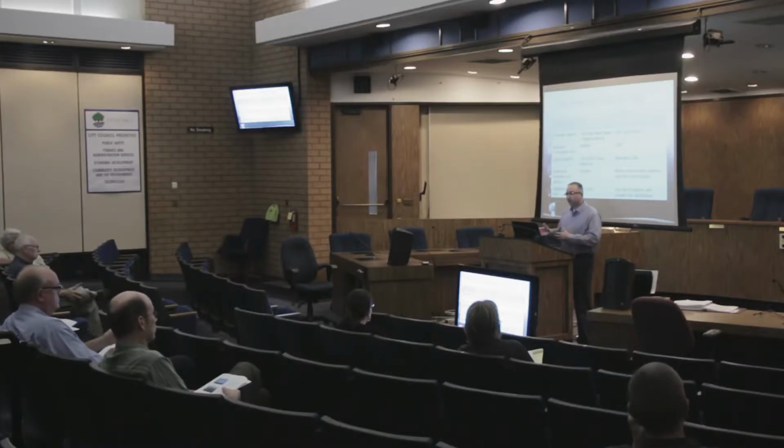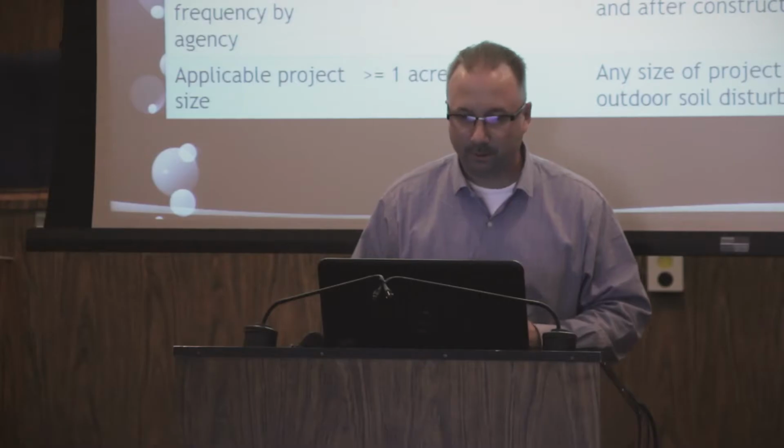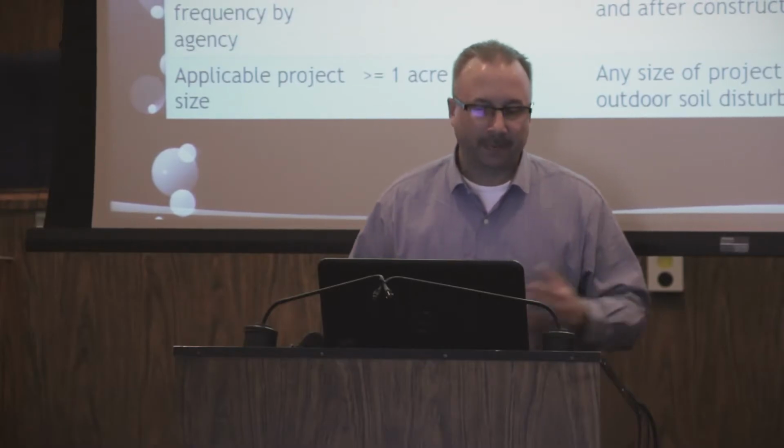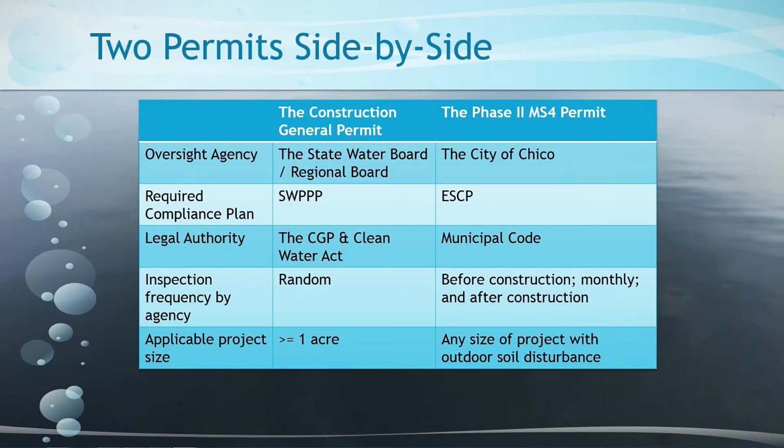However, we're going to see here in a moment that even very, very small projects under this municipal permit have to submit a similar document. Not exactly the same, but similar in intent anyways, and it's an Erosion Sediment Control Plan, ESCP. Now, legal authority. Under that construction general permit, the legal authority is the Clean Water Act.